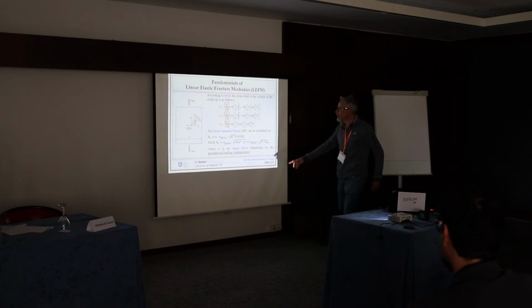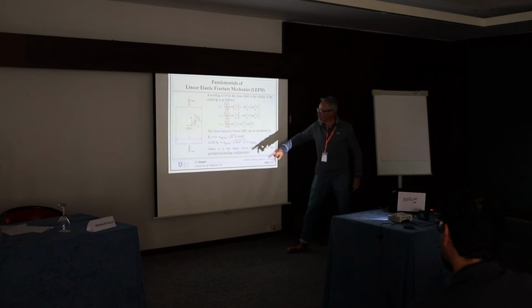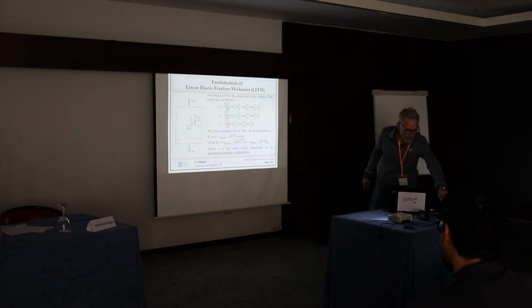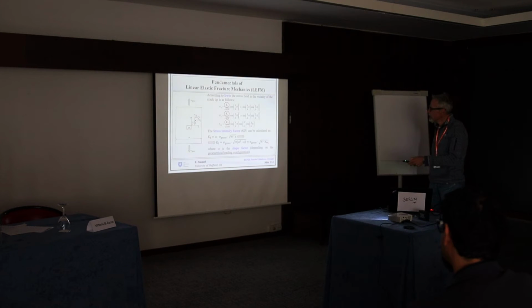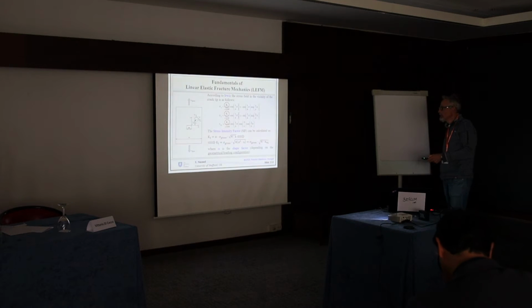This is the engineering definition we usually use for the stress intensity factor. I have a pointer here for the stress intensity factor, and this is the remote stress, alpha is the shape factor, and this is the semi-crack length. We can easily rearrange this definition, and we can introduce also an equivalent length of the crack by simply bringing the shape factor into this term.